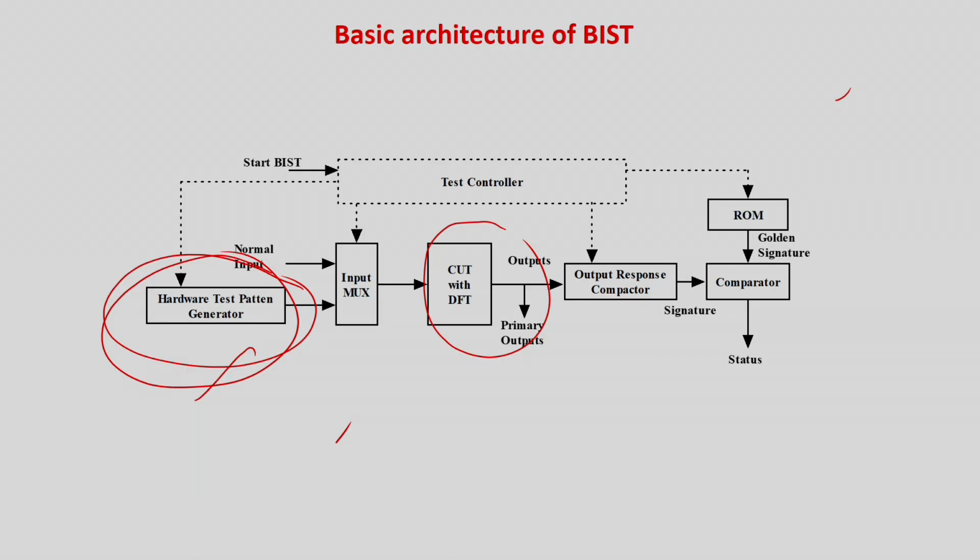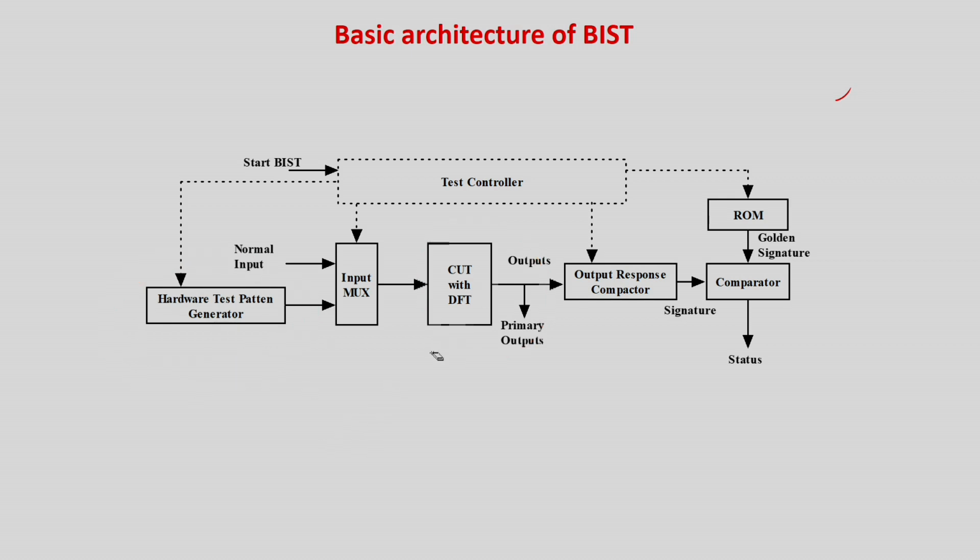There is very low area overhead test pattern generation by something called linear feedback shift registers, as we will discuss in detail today, which can give random order patterns. Random order in the sense that the order of the patterns may not be as you desire, but all the patterns will be generated, just in a different sequence. We will show that a very low area overhead hardware test pattern generator can be designed, so that you can have a built-in self-test with maybe around 50% level of confidence compared to the ATE, but you can do the test.